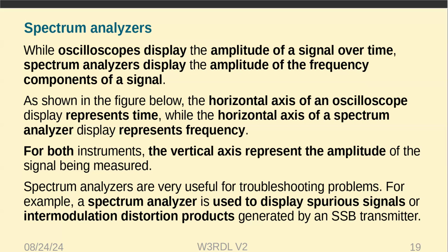You can make amplitude measurements with the oscilloscope. It'll tell you the peak values. You can make time measurements to find what the frequency of the signal is, and see if the frequency is changing. You can see distortions in the wave. If it's not a pure sine wave, it means you've got some other frequency components in there to make it all funky looking. Okay, thank you.